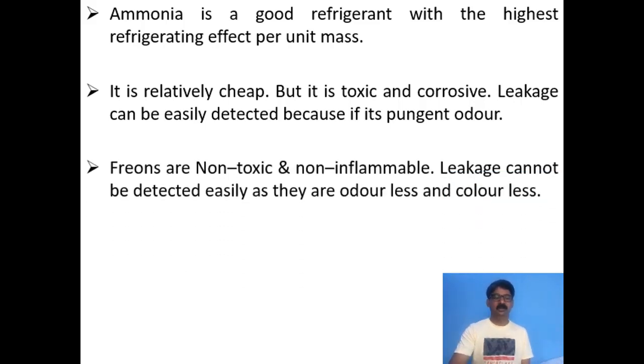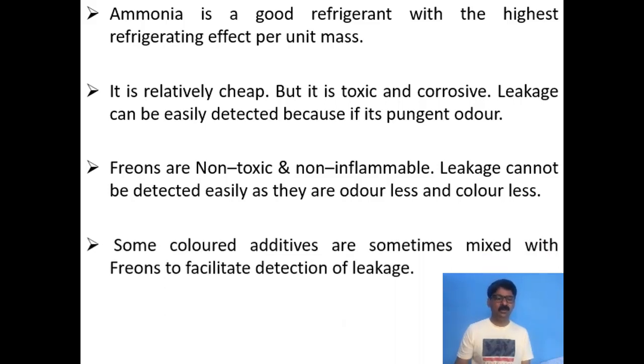Now coming to the freons, they are non-toxic and non-inflammable, which are advantages compared to ammonia. Ammonia is toxic, but freons are non-toxic. But the disadvantage of freons is that leakage cannot be easily detected, because they are colorless and odorless. So what we do is sometimes mix colored additives with the freons to facilitate detection of leakage. So this is the discussion about the various refrigerants.